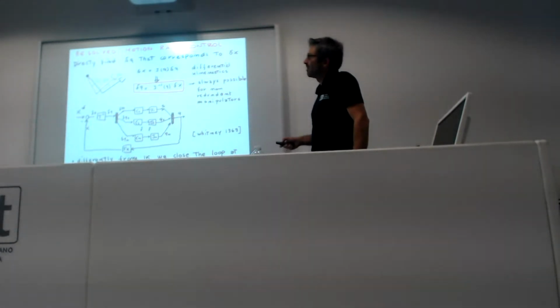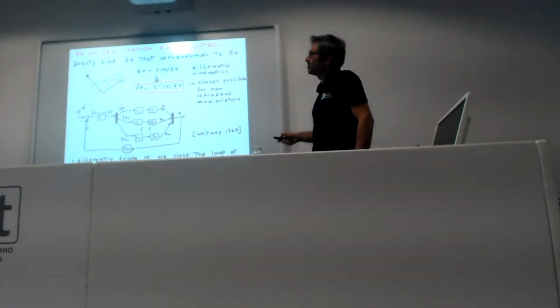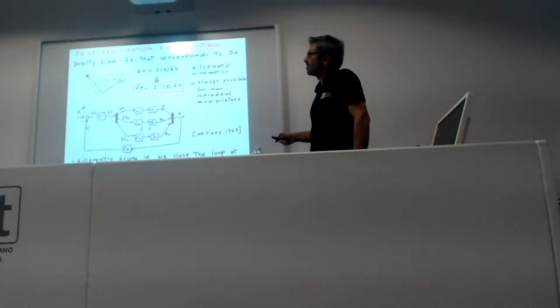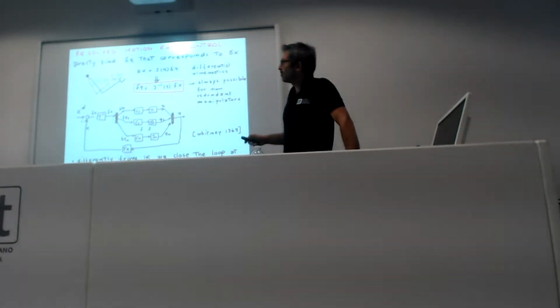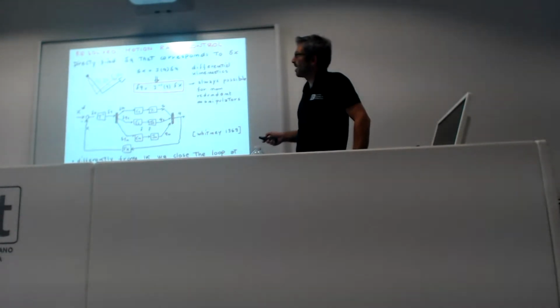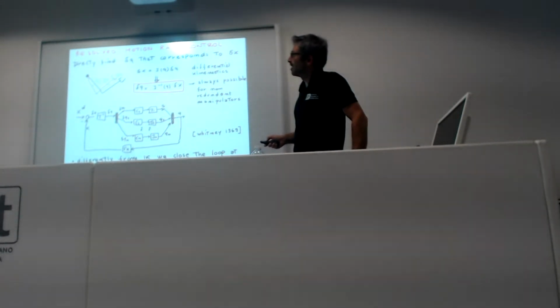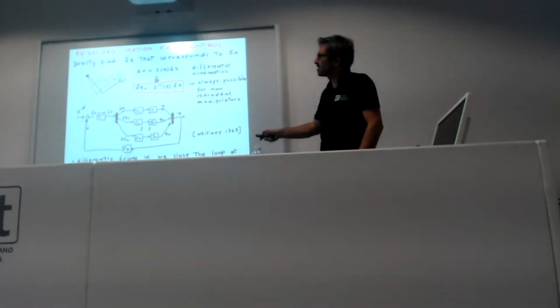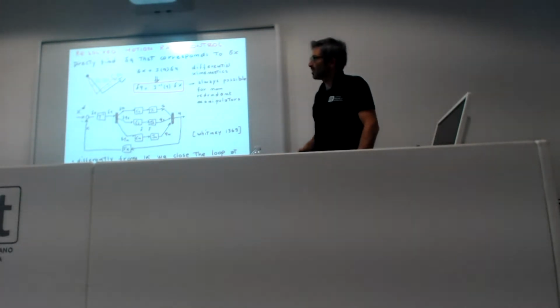Let's say you have, in this case, a position controller or a PD controller in the joint. Or if you have inverse dynamics, you could have coupling, so you can have an inverse dynamics plus PD. You can have whatever we discussed last lecture inside here.